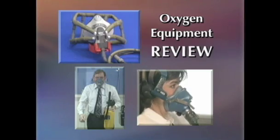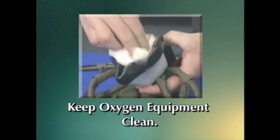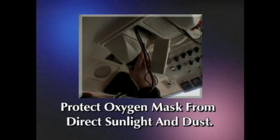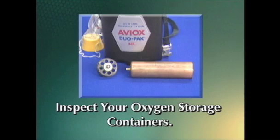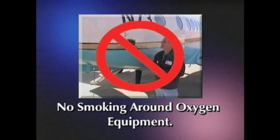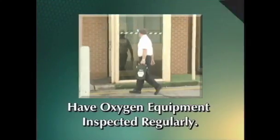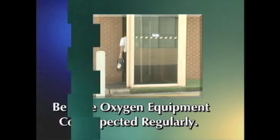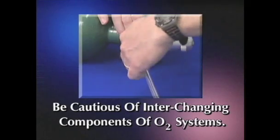Operational precautions when dealing with oxygen. Keep your oxygen equipment clean. Protect your oxygen mask from direct sunlight and excess dust. Inspect your oxygen storage containers. Do not allow anyone to smoke around oxygen equipment. Make sure your oxygen equipment is inspected regularly. Be cautious of interchanging components of oxygen systems.